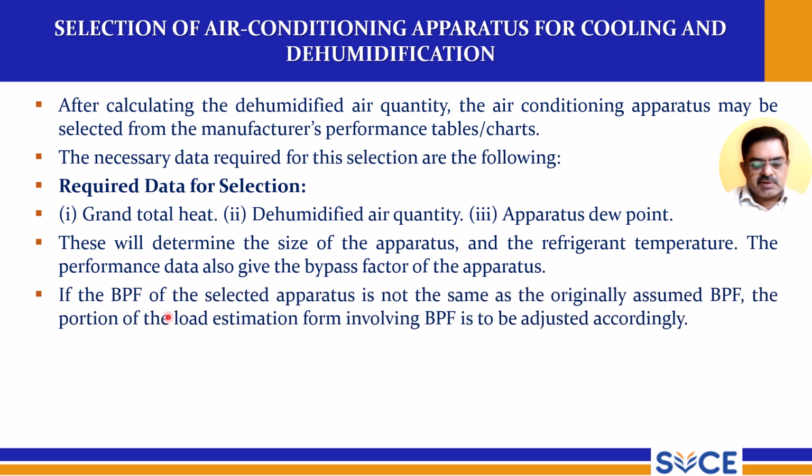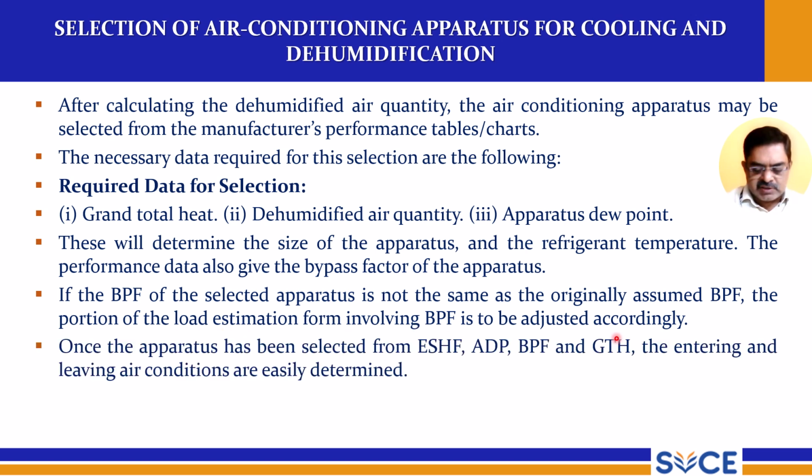If the BPF, that is bypass factor, of the selected apparatus is not the same as the originally assumed BPF, the portion of the load estimation form involving BPF is to be adjusted accordingly. This is a very important sentence here.